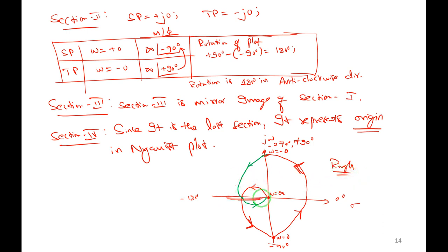And you can see here, this Nyquist plot is intersecting the minus 180 degree reference line, where I get point Q. So here omega equal to omega PC. What is omega PC? I have to find out. And what is the coordinate of point Q? I have to find out. Because the Nyquist plot is intersecting the negative real axis, I have to calculate the omega PC value and the coordinates of point Q. And this is the origin. Okay, that is step 4.